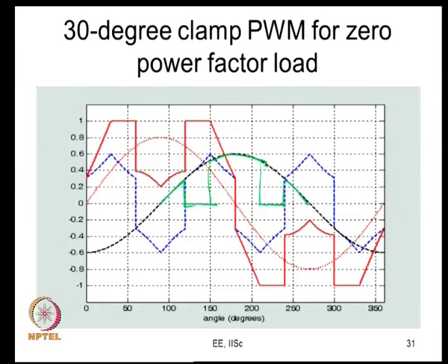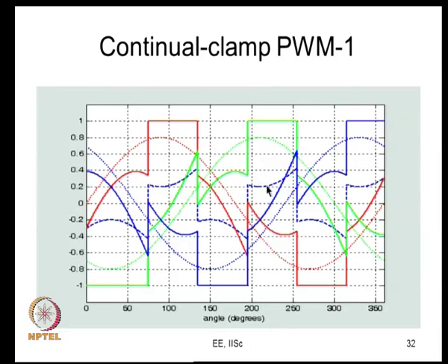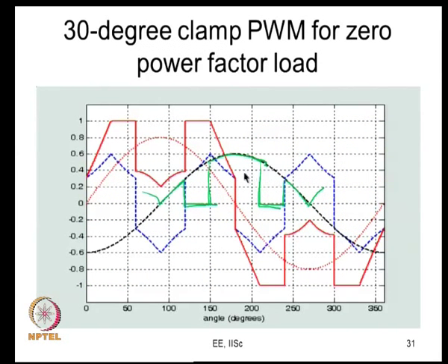This is 1/2 cycle of the energy loss, this is 1/2 cycle of the energy loss. So, you see that it starts increasing this side again. From here to here, you cannot clamp close to the peak. So, if you call this 0, you are clamping between 30 to 60° and 120 to 150°. Ideally you want to clamp between 60 to 120, it is not possible at all. So, you are doing this now.